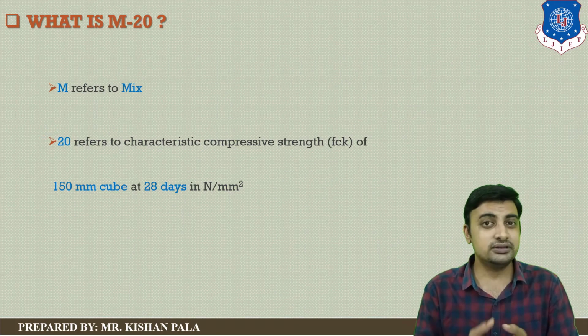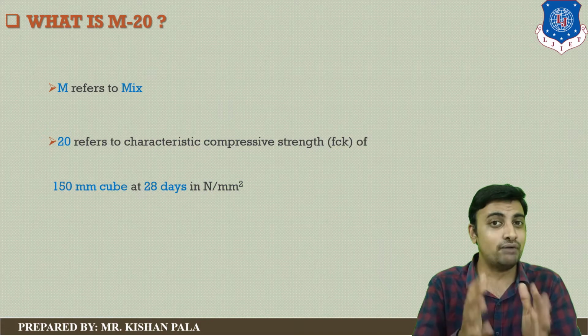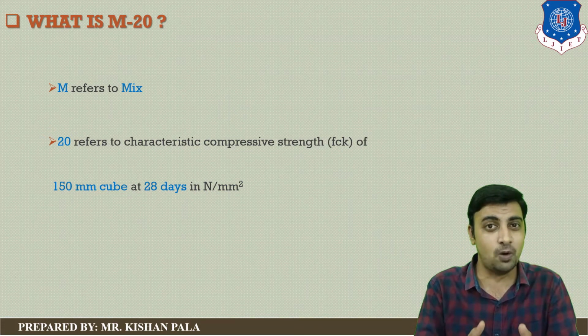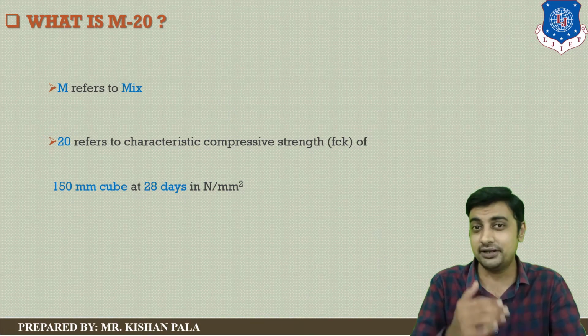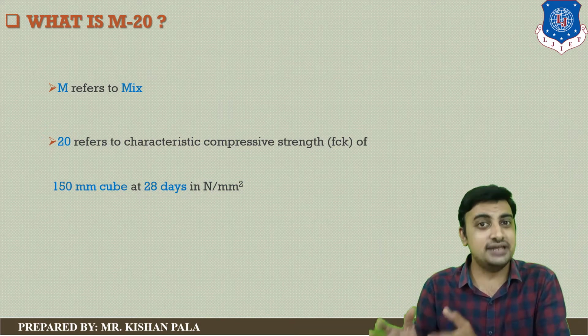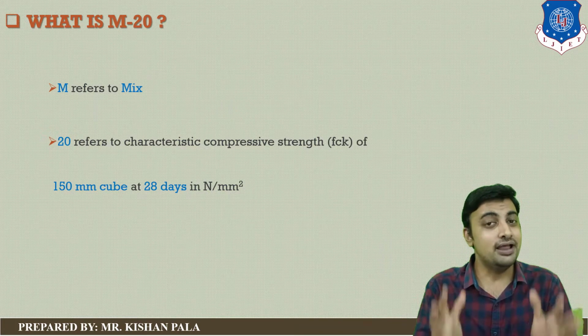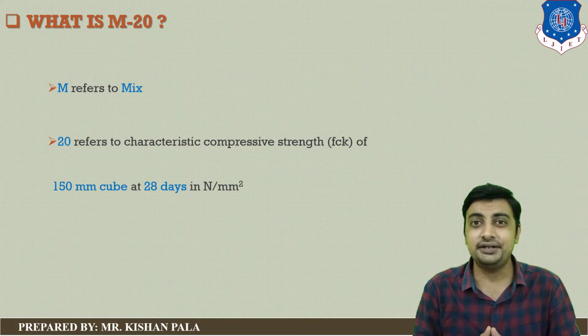Before starting any type of structure, you have to find out the hardened property of the concrete mass. It means after the mix design, you have to do trial testing, and in the trial testing you have to identify the compressive strength of the concrete mass.